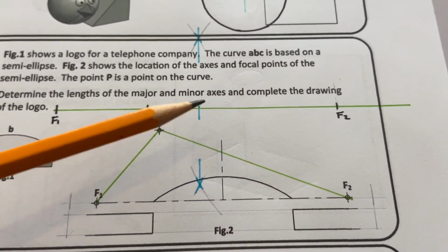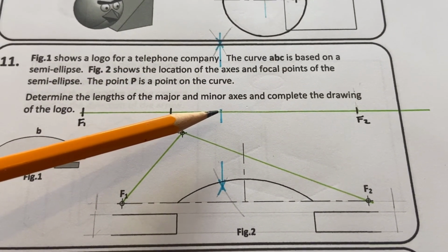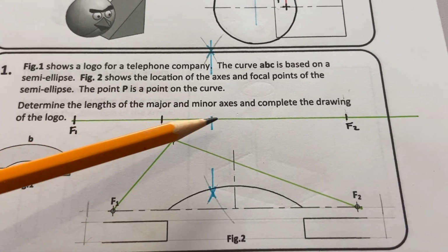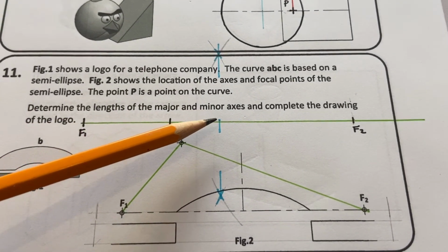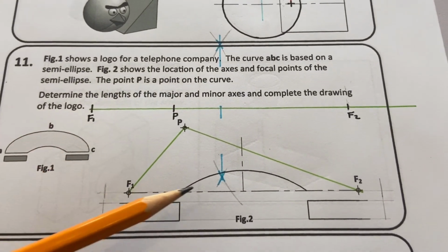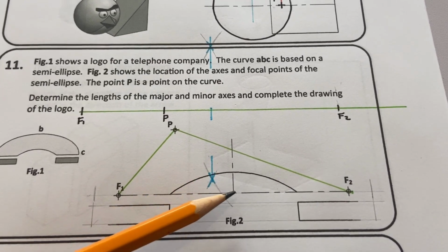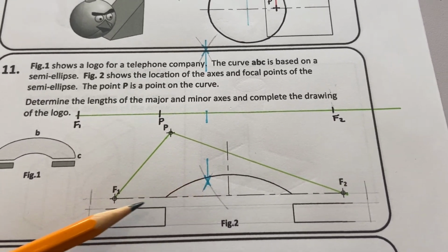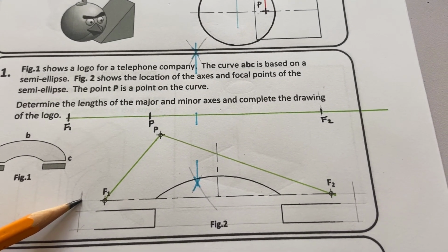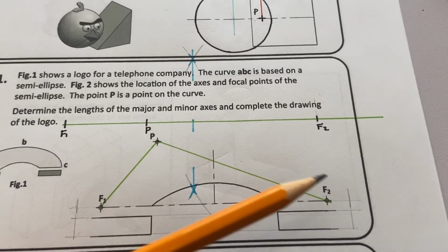So we take our compass now and we bisect that line to get the midpoint of the line. So from there out to F1 is half the major axis. We take that distance on our compass from this point to F1, and from the center here, where the minor axis intersects the major axis, I mark that distance out there, and that will give me the end of the major on this side and the end of the major on this side.